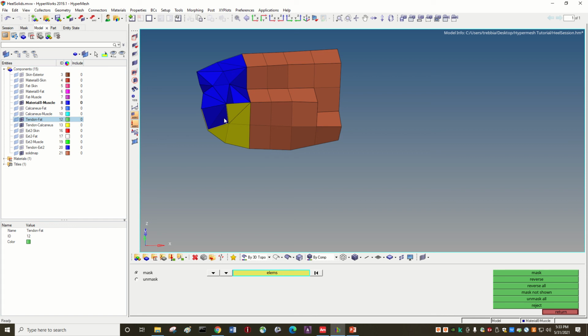And you need to find a solution in the case you have incompressible materials, because these might create locking problems. But in ANSYS there should be possibilities to fix this locking problem. So this will end this video. In the next one, I will show you how to export your mesh.